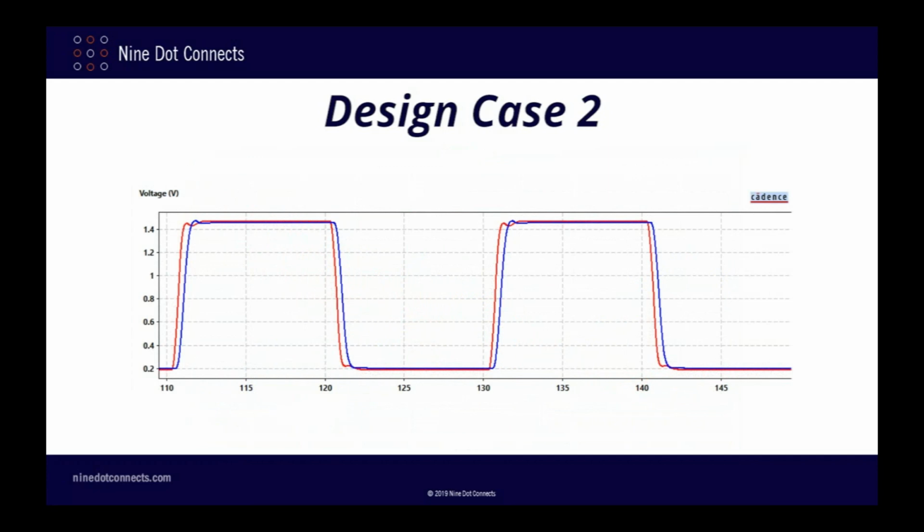Surprisingly enough, looking at the time domain, we don't really see much change. The signals still look pretty good, at least at this scale. There is a very slight change in the ringing from the first design case, but it really doesn't look like having uncoupled reference planes at different voltage potentials is having much of an effect in the time domain.